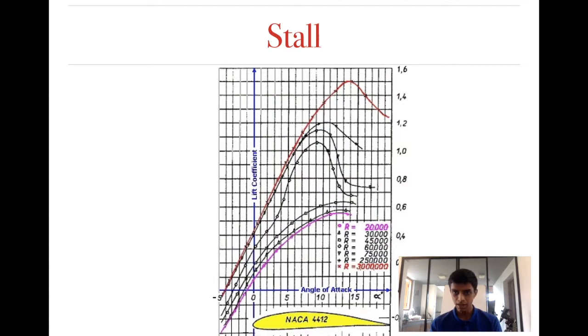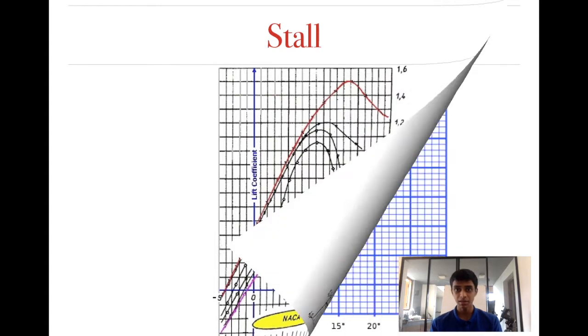But take a look at the graph near 16, 17, 18, 19, between 19 and 20, you can see that the graph suddenly disappears. This means that there won't be any lift after that point, meaning that that is the stalling angle. We can't exactly describe this with this graph, so hang on, we definitely need a better sketch for that.